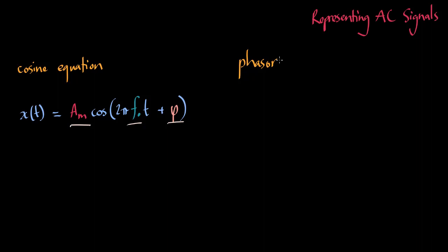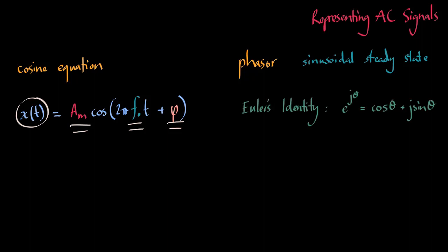These are special and require us to make a very key assumption that the system is in sinusoidal steady state. What this means is that these three parameters are unchanging, that is, time invariant, meaning that our x(t) is stationary. Phasors can be derived by rewriting the equation using Euler's formula. As we are only interested in the real part of the signal, we can ignore this right half.